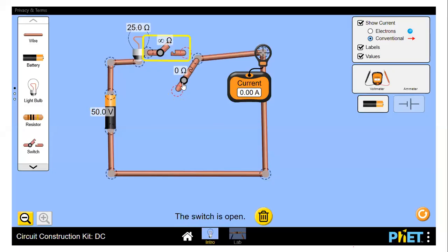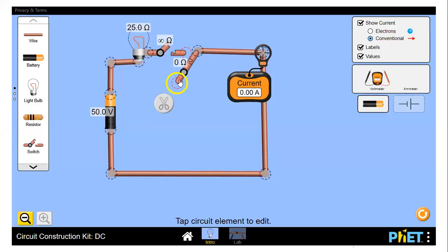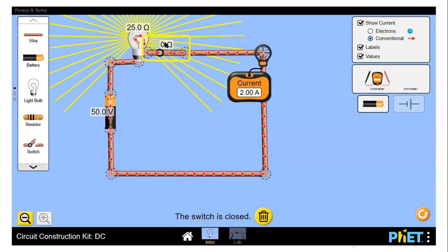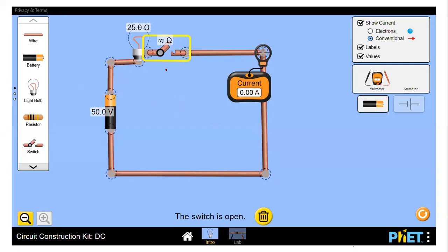This one is another switch. Okay, I'll remove this part. So this is open. When I turn it on, it turns on fine. Now look at this. What if you want to replace this lamp? Accidentally, if you touch this terminal, you receive a shock, right? Though this lamp is not glowing right now.